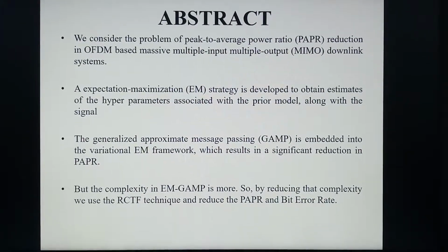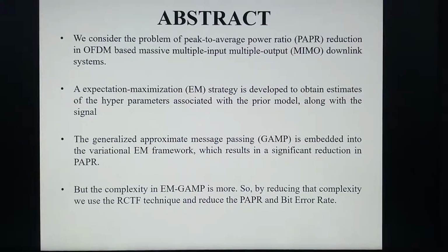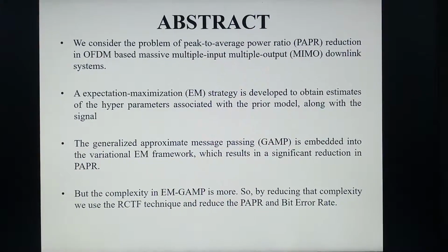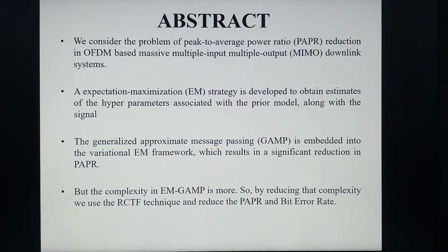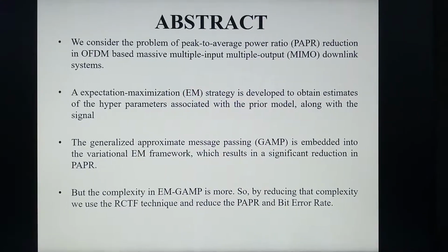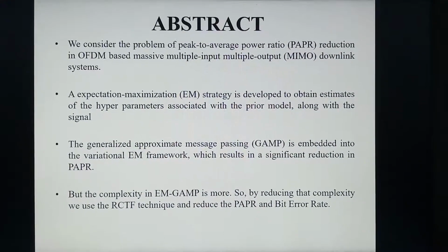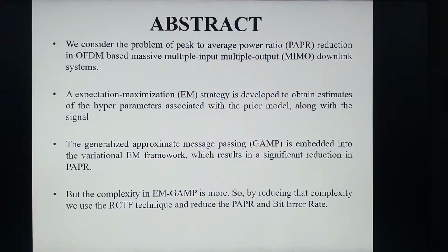In this, the complexity is high. So, to reduce that complexity, we are introducing a technique, RCTF, and by using this technique we reduce the PAPR by up to 6.5 dB and also calculate the bit error rate.